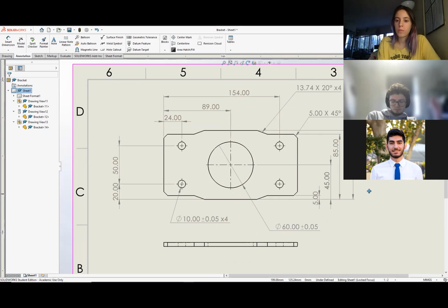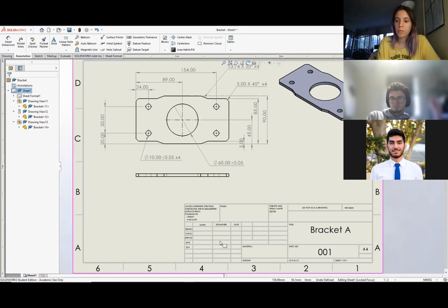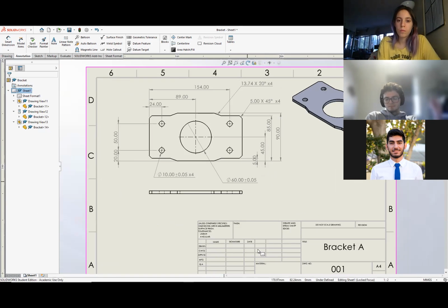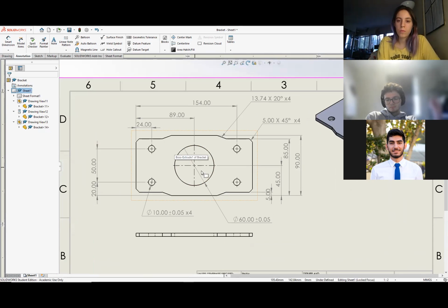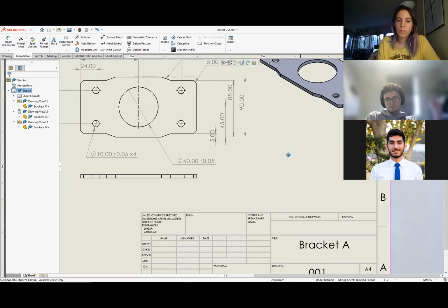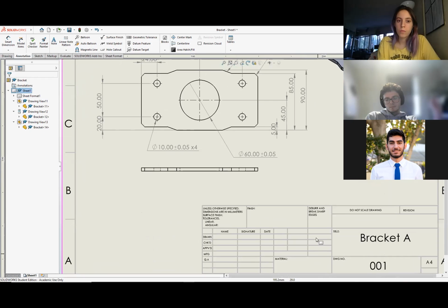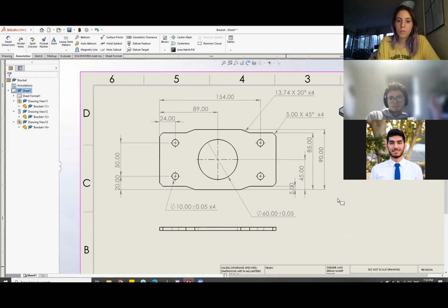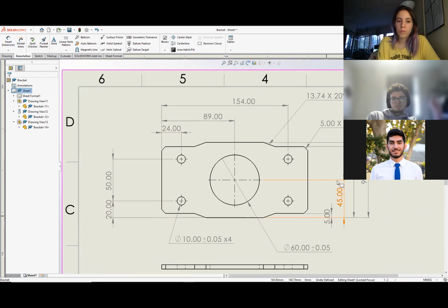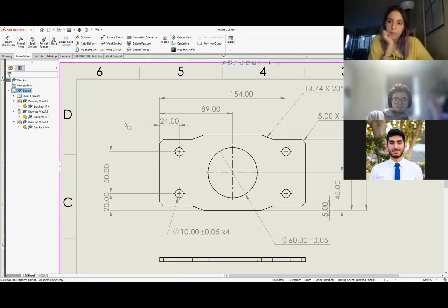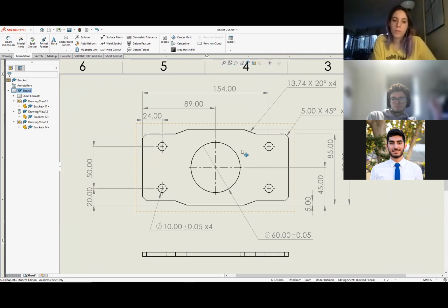What we could do instead is make a note somewhere down here that specifies, hey, unless specified, assume all tolerances are 0.02 or something like that. That is fair game. So I won't write that down right now explicitly, but we'll go ahead and assume that's the case. So all of these length measurements, we'll just assume they're toleranced to say 0.05 or something. So that's that.